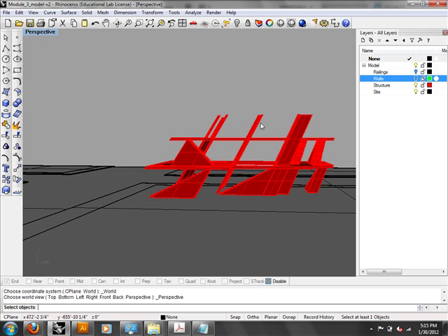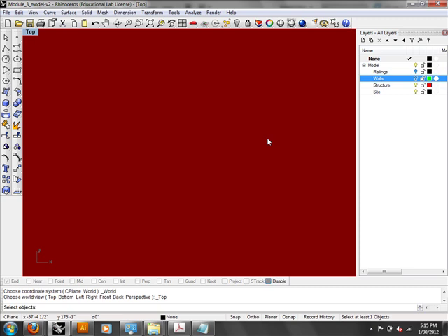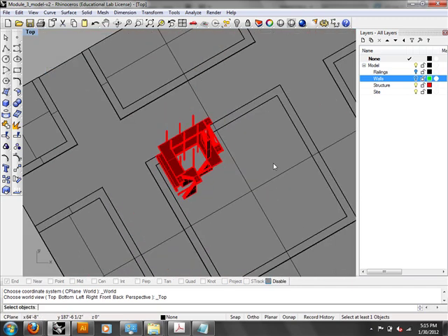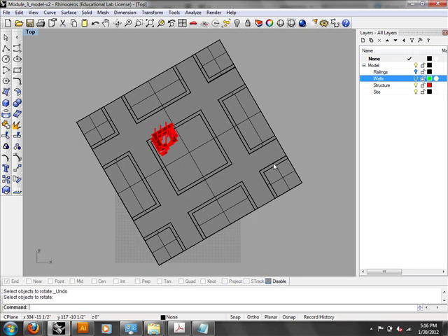Yeah, your eyes aren't deceiving you, okay? This is a hack, okay? What it does is it actually shears the building 45 degrees so that when you're in a top view, it rotates the world 45 degrees and shears it, and that's what gives that to you, okay? So that means a couple of things have to happen. One, save your file before you do any of this stuff because it will destroy your file, okay? And 2, you're like, well, that's great, Nick, but how do I get the other sides of the building? You should be asking that.